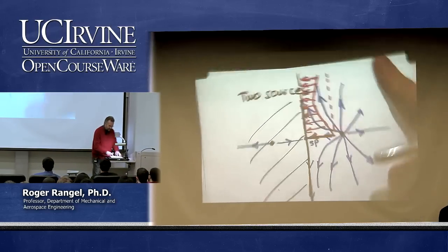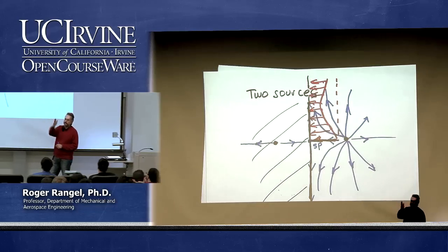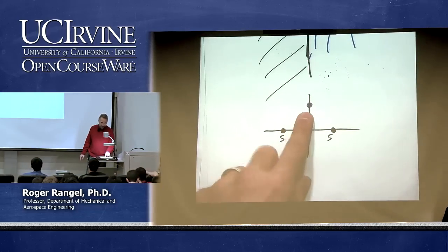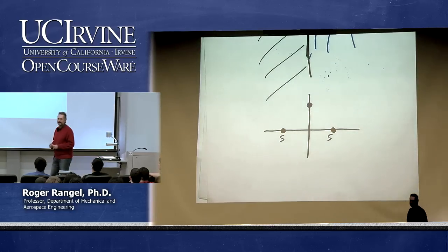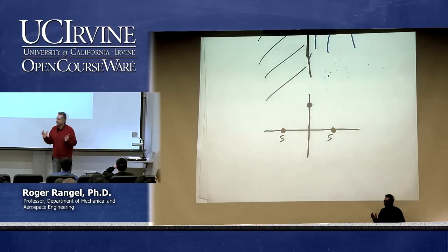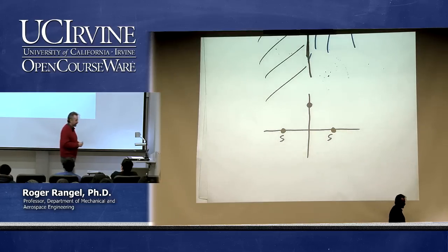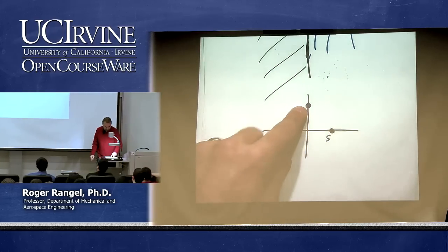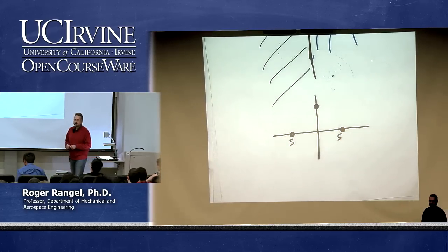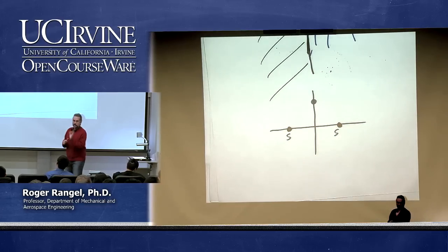And we just agreed that it's 0 at the stagnation point and then it increases to then decrease again. But it's not 0. So how can I find the velocity there? Think about each source separately, because remember, we use the principle of superposition. We can superpose what each source is doing separately. What's the velocity at the blue dot due to the source on this side? Just forget the source on the left for a second. Just think of the source on the right. What's the velocity on the blue dot?